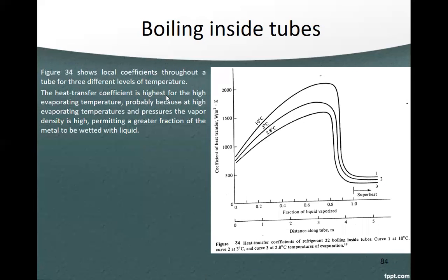So, the heat transfer coefficient is highest for the high evaporating temperature, probably because at high evaporating temperature and pressure the vapor density is high, permitting a greater fraction of the metal to be wetted with liquid.